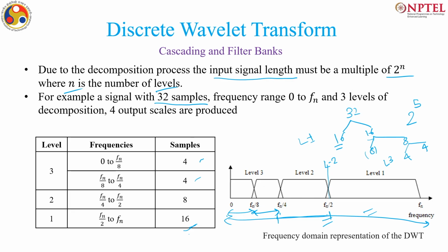Here I have shown up to level 3. So, this detail again I can store, and this approximation will again be subjected to give 2 and 2, and this detail. So, this is level 4, and the last is I get 2 in level 5. So, this is 1 and 1. This is how this signal is split in wavelets, and each time you see that the scale is different.